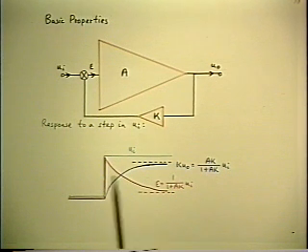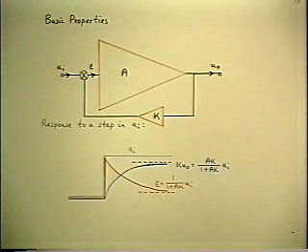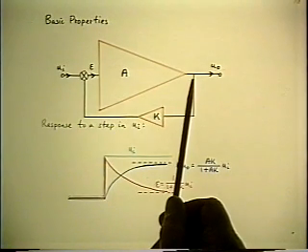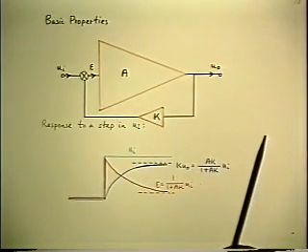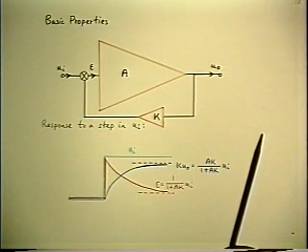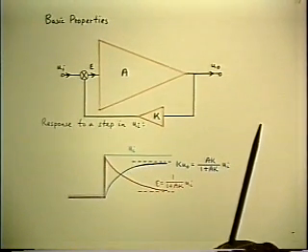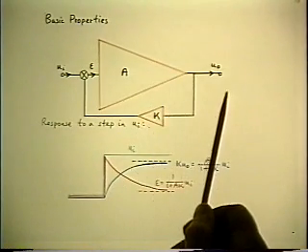Now, it's a little more useful to have this physical interpretation when you think of some typical numbers that may be involved in this. Suppose the forward amplifier is an IC chip. It's got loads of gain, 90 dB, 100 dB, 110 dB, lots and lots of gain. The maximum dynamic range of the output is limited by the power supply, plus or minus 15 volts maybe, or in your case plus or minus 1.5 volts perhaps. Whatever it is, it's limited.